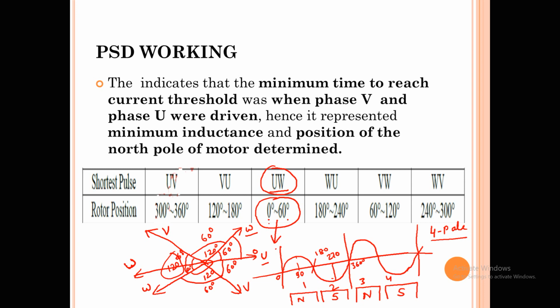The same way, if you're sending high frequency voltages to the motor and you're sensing this particular sequence, whatever position your rotor is in relative to the stator, it is between this particular angle, somewhere at 60. At that time you energize your sequence in such a way that you rotate your motor in a perfect startup and in a forward direction.